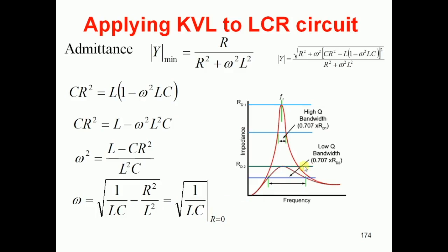And the quality factor will determine how sharp your impedance with frequency appears. So here you have maximum impedance as a function of frequency, and on either side of this the impedance goes on decreasing. For maximum impedance which appears in the denominator, if you plot in terms of current, the current will be minimum for maximum impedance. This is how we complete the discussion of the LCR circuit.